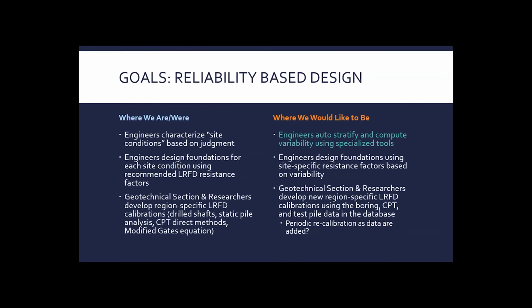In terms of our reliability-based design, I think most of us, at least in state DOTs, are in the same boat. We select our design profiles or site conditions based on our own engineering judgment, and then we design foundations using recommended resistance factors.